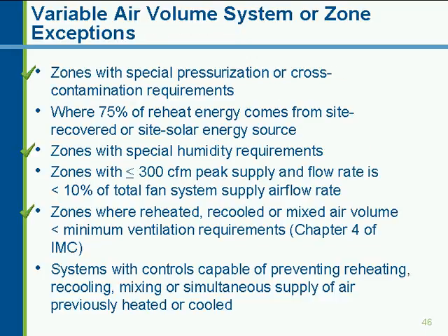On the VAV air volume system or zone exceptions, please define special humidity requirements. Zones with special humidity requirements. This term is not defined in the IECC or really anywhere else that I am aware of. So I guess it would be up to interpretation of the jurisdiction or whoever the ruling authority in the situation would be.